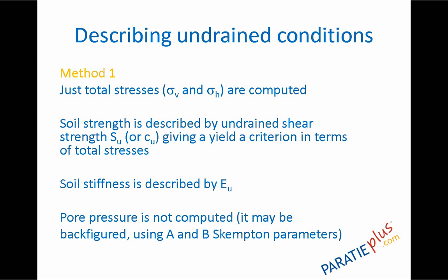In this traditional framework, pore pressures are not computed because they are automatically incorporated in the calculation of total stress. And they may be estimated following some proposal, like using the A and B pore pressure parameters proposed by Dr. Skempton.